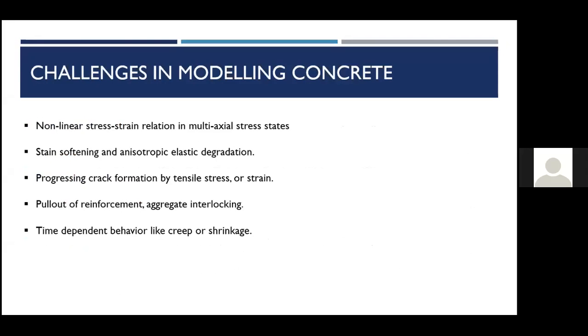Now coming to concrete, we know that concrete, unlike steel, is not homogeneous. Concrete is a particulate composite of large aggregate and mortar mix, that is a composite of sand and cement. The physical behavior is also rather complicated, and it strongly depends on many factors like water cement ratio, aggregate size, shape distribution, cement type, temperature, and much more. So we consider concrete to be homogeneous and initially isotropic. In reality, we have a vast number of micro cracks at the aggregate boundaries itself due to shrinkage and very complicated stress strain even before we put any load on the concrete structure. So modeling concrete is very complex.